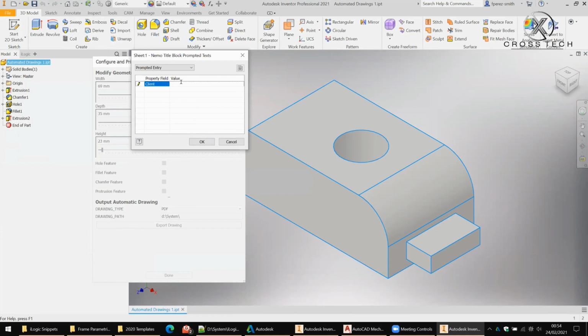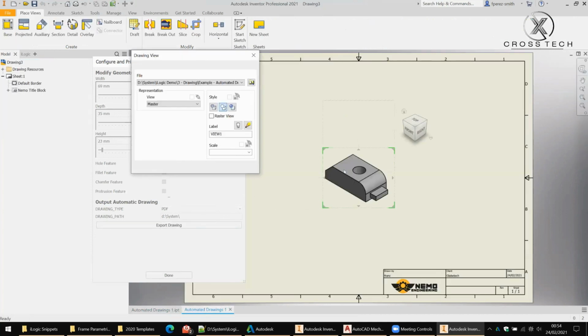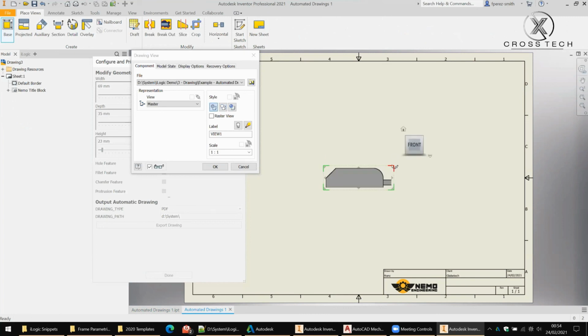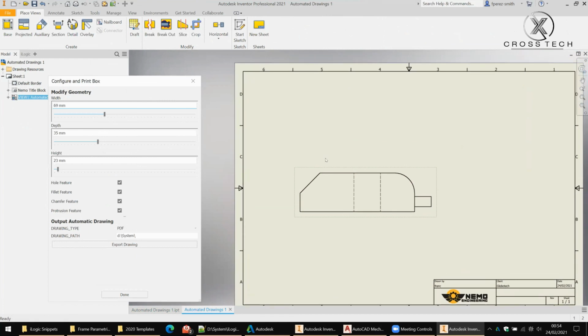Beautiful. Clients, we might say, let's go ahead and say that's Globotech. No affiliation with Globotech if it happens to be a company. Wonderful. And here we've got drawing. Lovely. And we're going to go ahead and add in some dimensions. So specifically, I'm going to add in a dimension that governs this fillet and maybe this chamfer here.